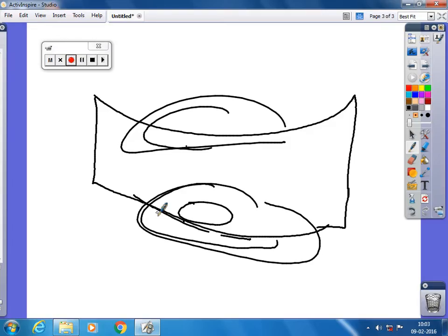But if the knot is situated on the top of a beam, the weakening is very little. It doesn't reduce the strength much. But when the knot is formed in the bottom of the beam, that is in the tension zone, it reduces the strength and weakens the beam. But in the compression zone, it doesn't affect that. Because it is weak in the tension zone, but good in the compression zone. That's the reason, if the knot is formed in the tension zone, it reduces the strength. Clear?